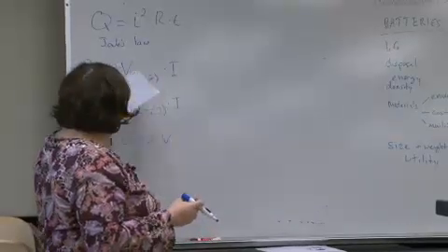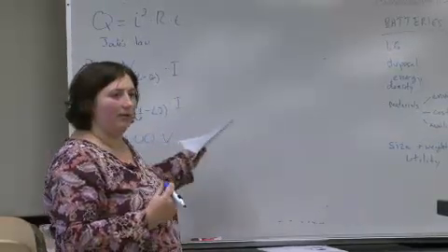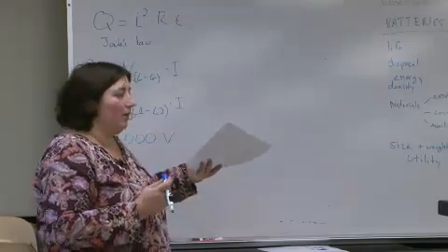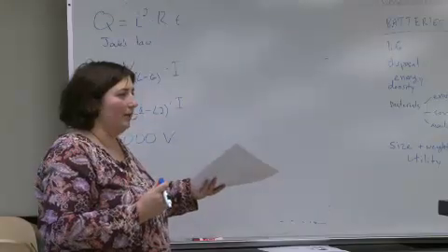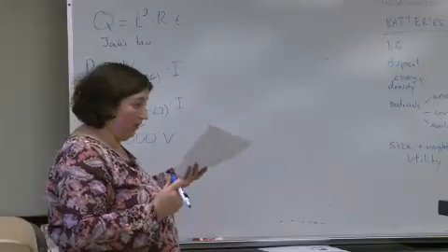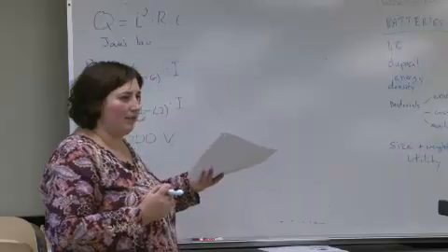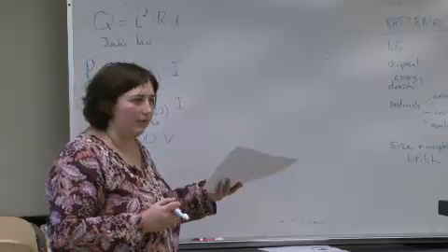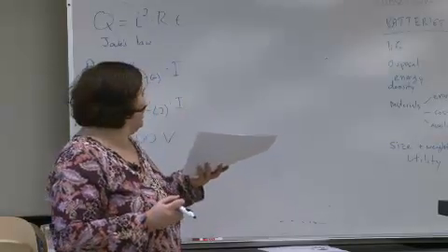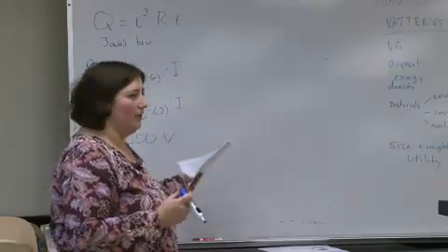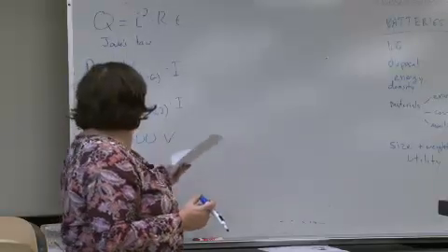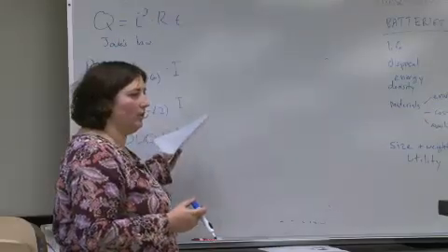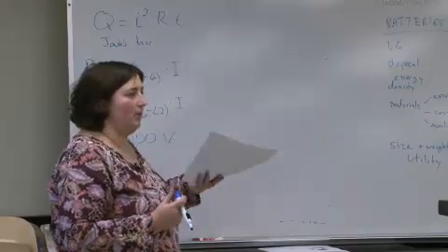So that is great in a macro grid, right? We can bump up the voltage, super, and we're all set. However, in a microgrid, bumping up the voltage, transforming the voltage, is really, really expensive. So in a microgrid, you don't do that. You just use your given voltage, which saves you a lot of money, but also means that line losses are huge. And so in that case, if you can't change your voltage, what is your loss based on?